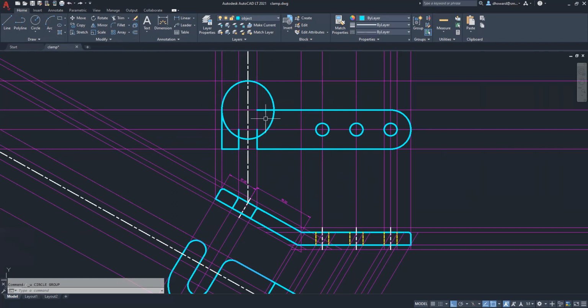I should offset to its outer edge though before I do that. So this ellipse that goes in this slot, its standard radius, as you can see in this view, is 13. So let me offset this line here 13 backward.